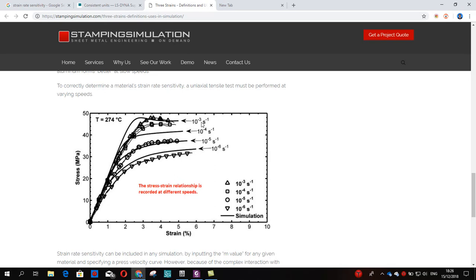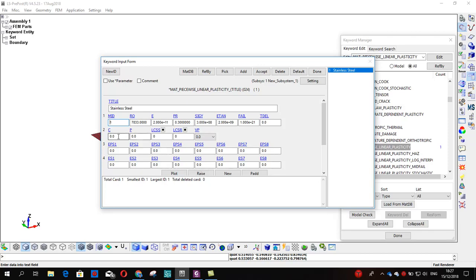Okay, if we put it simply, we can say that the material behaves differently at different speeds. So since our problem is like a blast wall, we have explosive, and it is a very high velocity problem. That's why we need to take into consideration this strain rate effect if we want to get a very accurate result. So we go back here. Now, most people use C and P parameters. Okay, we have just two parameters here so that the strain rate effect is taken into consideration.